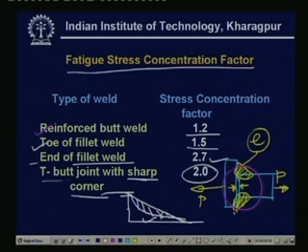Now, let us come to the conclusions. What have we learned? We have learned the different kinds of welded joints and how to design them. Designing is very difficult, and we use the thumb rule that it is only at the throat where the stress is maximum, and we design the welding considering only the throat cross sectional area. There is various literature available. If you have a chance to look at some of the textbooks, you will find many such design problems given, you solve them. So, this is as far as the welding joint is concerned, and I end here today. Thank you very much.